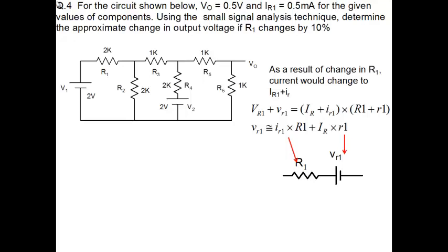You can see that it's a pertinent question. Why? Because let's say I take this particular circuit, analyze it, and I find V0 has a certain value. Now in the lab, when you use a resistor of 1 kilo ohm, is it precisely 1 kilo ohm? What is the last band that tells you? Tolerance, right? So when you have a tolerance of 5% or 10%, instead of 1K, you may get 1.1K, or you may get 0.9K if it's a 10% tolerance.